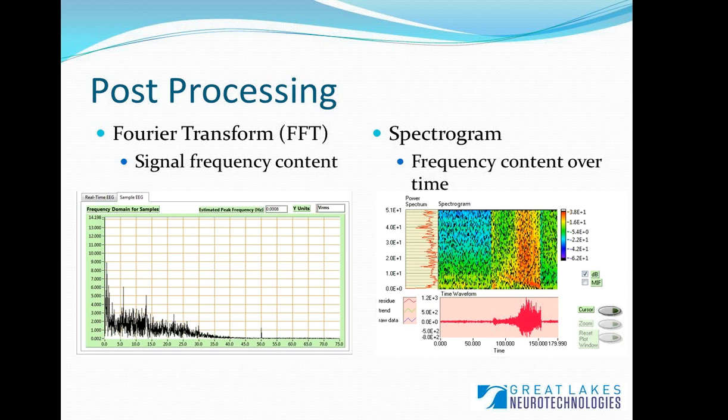So by looking at the FFT of a signal, you can quickly see that this particular signal has a strong DC or 0 hertz component, but also has peaks at around 1, 6, and maybe 13 hertz as well. We can also see that most of the signal is contained in frequencies below 40 hertz.